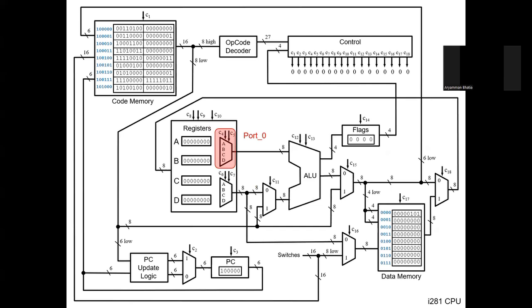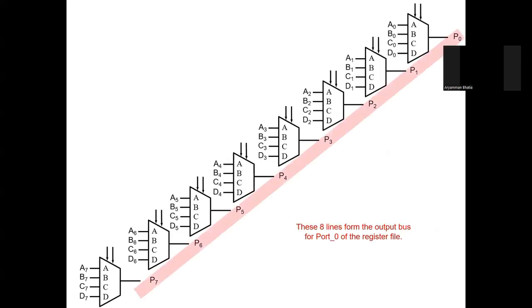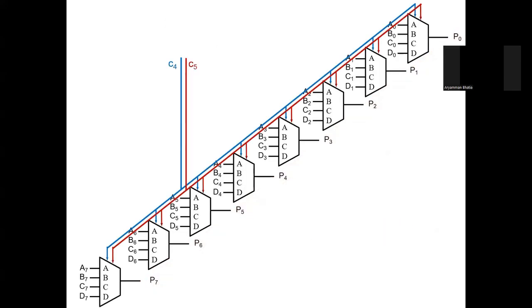Yeah, these are all the different registers. This is again the multiplexers, same type of logic. All 8 bits use individual multiplexers, but they are all controlled by the same control lines because yeah, we want to do it parallelly. We don't want to pass one bit at a time through a single multiplexer. We want to do things fast, right?